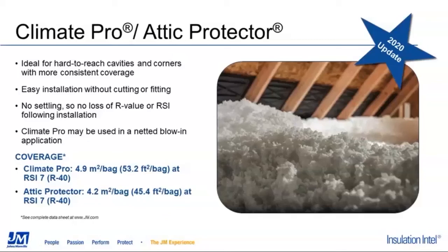This is a much faster and easier way to install insulation in your attic compared to using batt insulation. And I think you can visualize that, right? You have a person up in their attic manning the hose, simply blowing this in. You have another guy at the end of the hose in the machine putting product in there. It's a much faster way to do this than it is to use batts. This product does not settle. It fits around all those little nooks and crannies you would have in the attic.